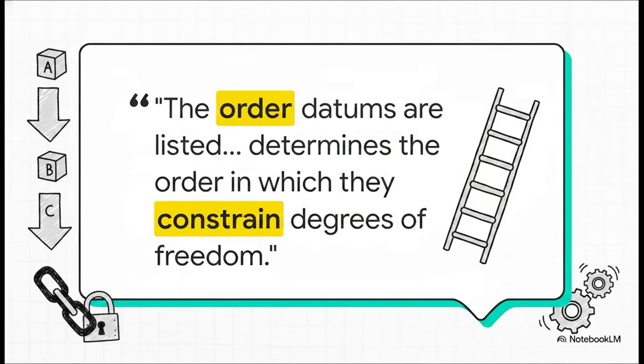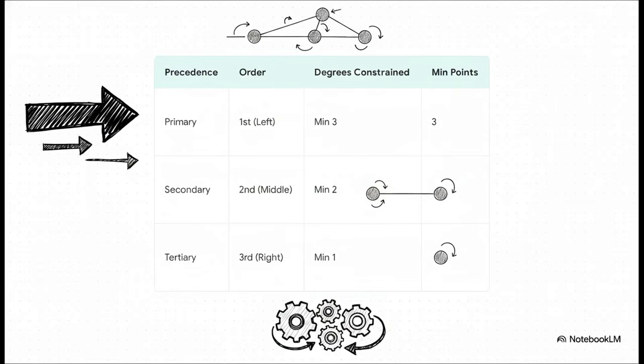Okay, before we go any further, I need you to pay super close attention to this next point. The order in which those datum letters appear is about to completely change everything you think this callout means. Datum precedence is read strictly left to right. It is not alphabetical.